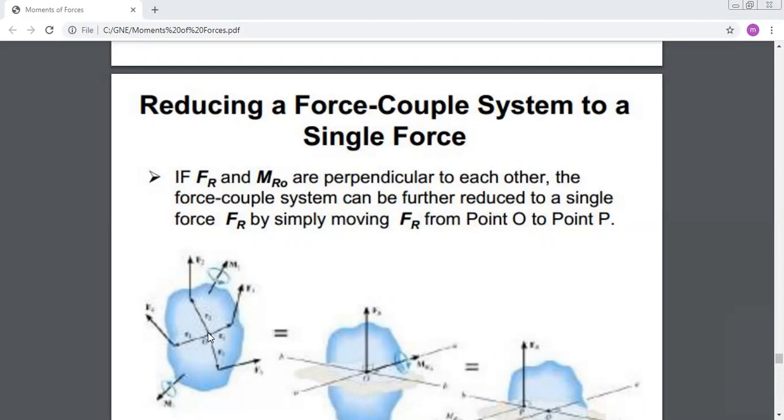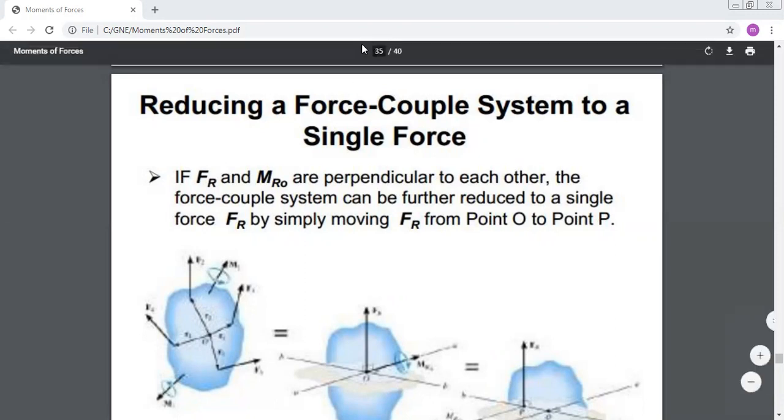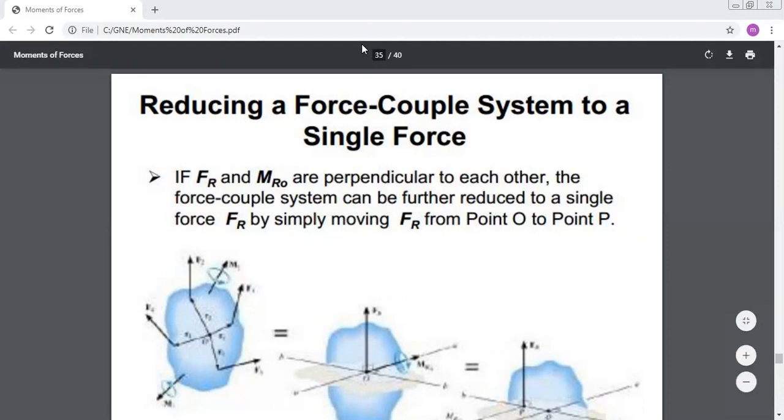these forces about O. Now, if you have couples, moment couples, what I mean by moment couples are moment created by couples of forces, and they are represented by moment vectors. Moment vectors, which are due to couple forces, are free vectors. This means that on this body, if I have this couple acting at this point, when I do sum of moment of point about O, I will consider it as it is. So I take M1 plus M2 plus moment of these forces about O.